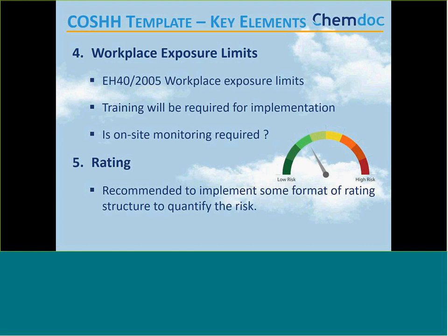I find it a very useful tool to put some kind of risk rating within the template to quantify the risk of this chemical, so that all staff, when they pick up this assessment, no matter what chemical it is, have one number or color area that they go to that very quickly tells them this is a high risk, this is a medium risk, based on the hazard of the chemical and the quantity you're using or the environment you're using it in, etc. There are a lot of different matrices you can use to come up with that rating.